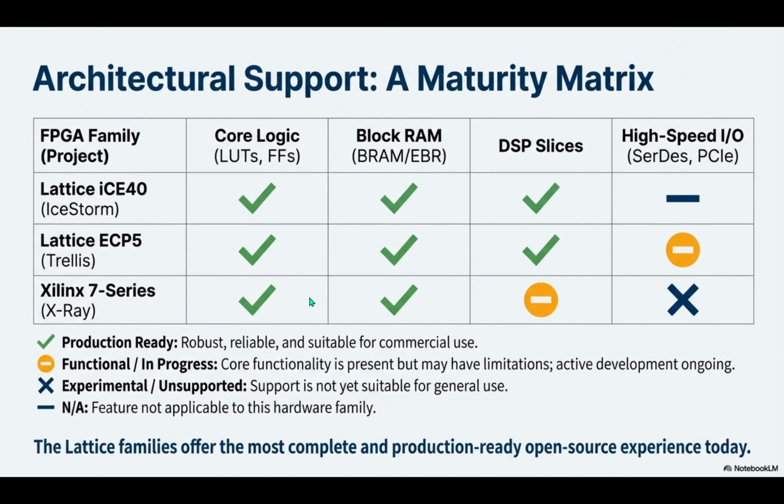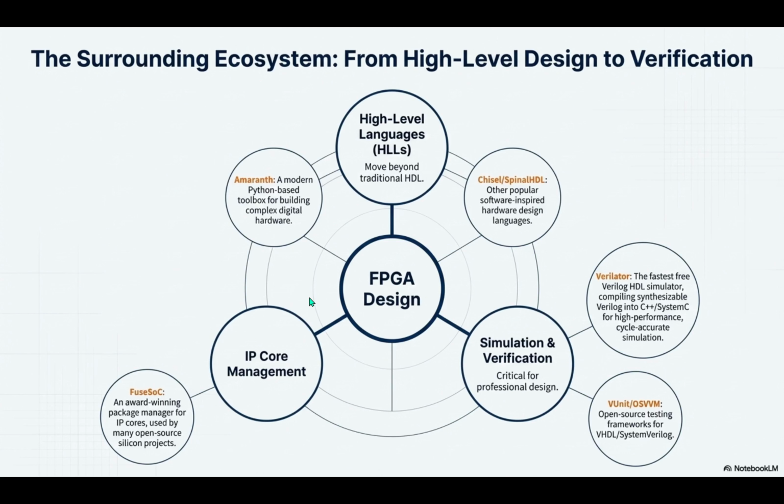Earlier flows were tricky. You needed complex command line scripts. But now, the FuseSoC Python package has emerged to provide a unified command line interface and a proper build system. It just simplifies everything. And it's not just the core flow, the whole surrounding ecosystem is thriving. You've got high-level languages like Amaranth and Chisel and professional simulation tools like Verilator and VUnit, which are essential for any robust design.